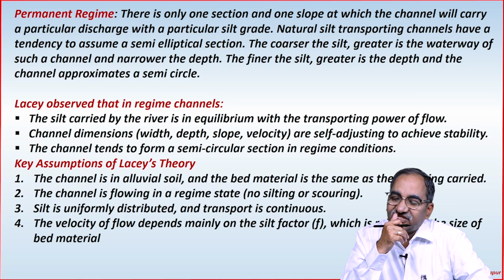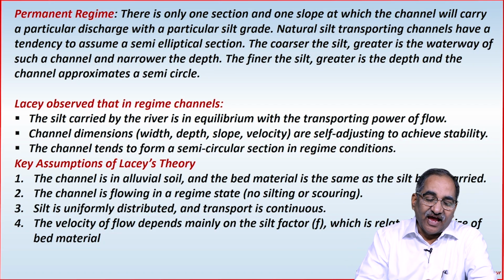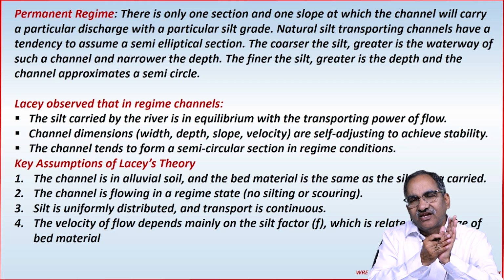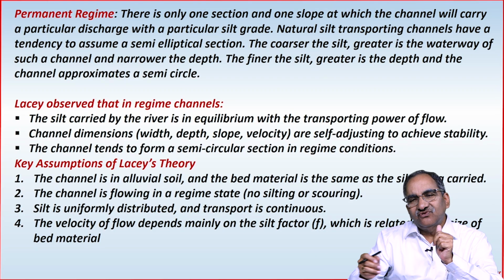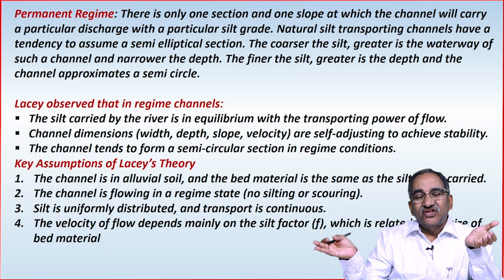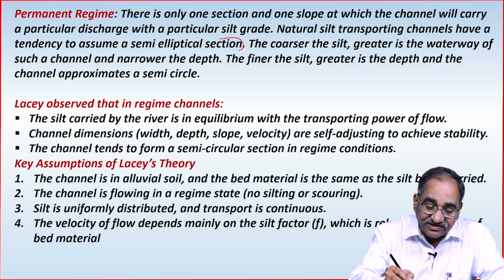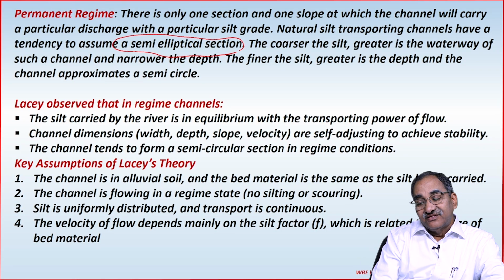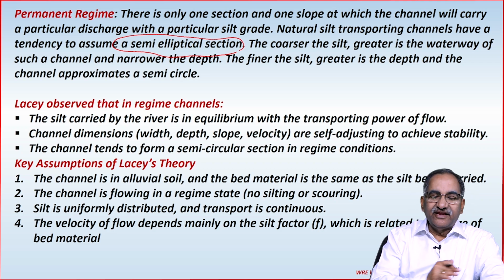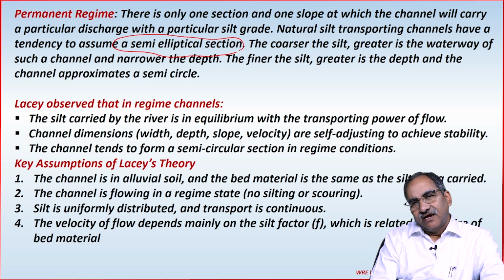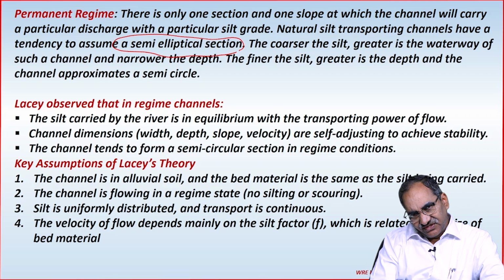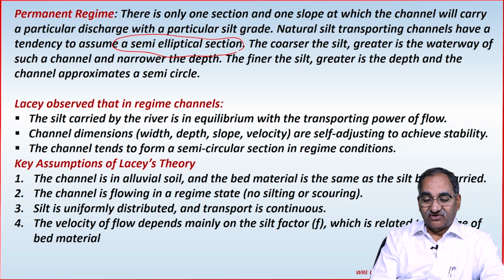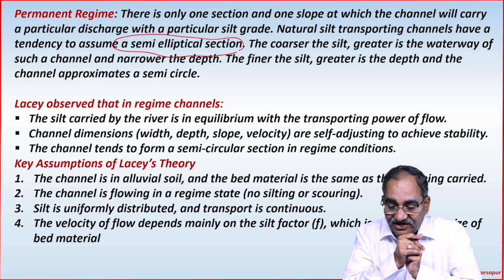Then natural silt transporting channels, generally unlined canals passing through alluvial soils, assume a semi-elliptical section. Lacey assumed that slowly any unlined channel passing through alluvial soil attains a semi-elliptical section.